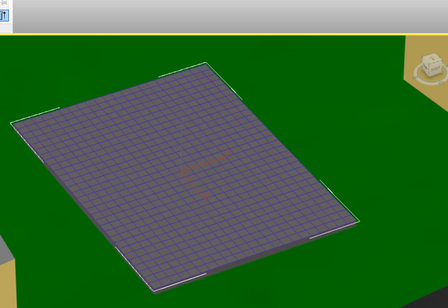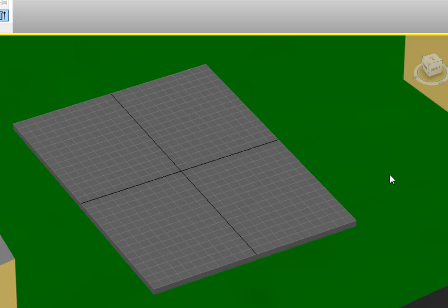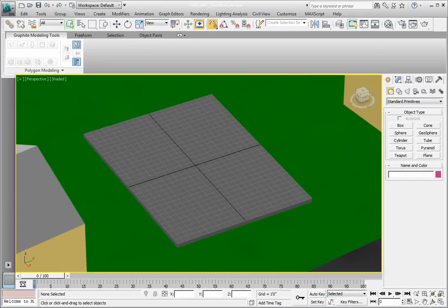Click on the green background object to deselect the grid. Don't worry about selecting the background object. The object itself is frozen and is not selectable. On the Command panel, make sure you're working in the Create panel. Make sure Geometry is the selected option. From the Geometry drop-down menu, choose the AEC Extended option. You'll notice several objects we can create. We're going to use the Wall object. Click on the Wall object in the Create panel.